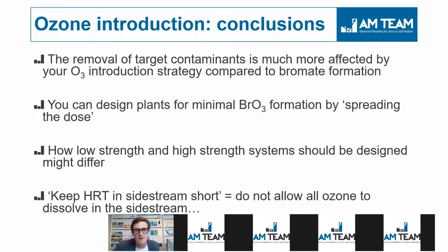There can be some differences in the target contaminants as well, but we are talking about like 1-2% or so. So it's very subtle, very small differences. Actually, you can design plants for minimal bromate formation by spreading the dose.